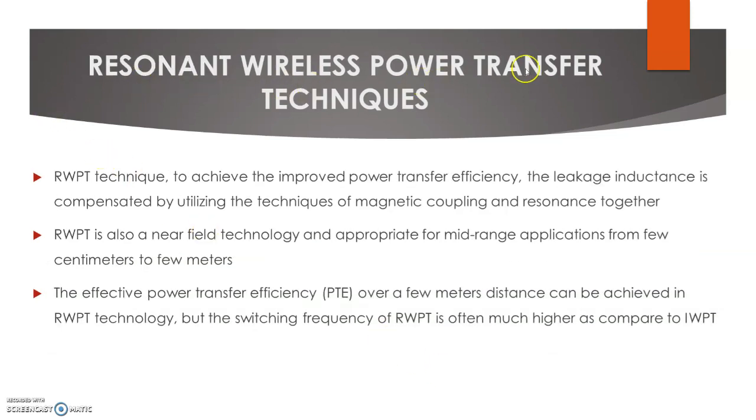Resonant wireless power transfer techniques. To achieve improved power transfer efficiency, the leakage inductance is compensated by utilizing the techniques of magnetic coupling and resonance together. RWPT is also a near-field technology and appropriate for mid-range applications from a few centimeters to a few meters.